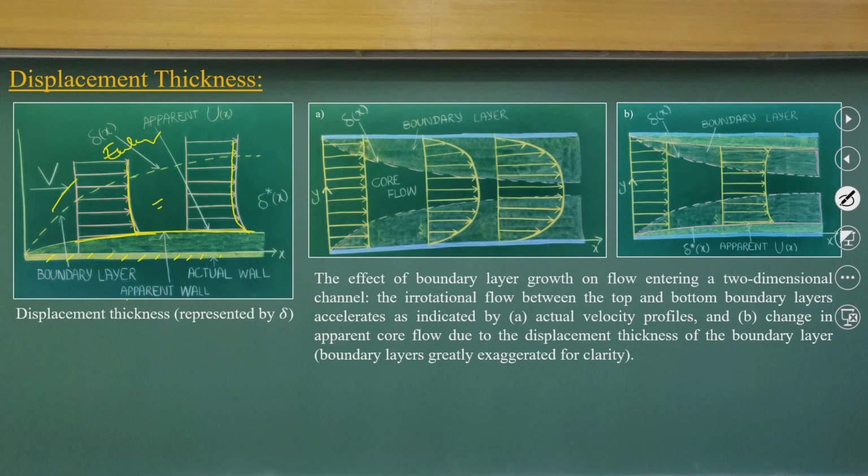The same way, if you look at two-dimensional flow, maybe pipe flow or flow between two plates, you can see the formation of boundary layers and these velocity distributions, and in the core region you can have constant values like this. As you go along, this core flow region reduces and we develop a fully developed velocity profile, starting from the entry, which is a uniform stream.